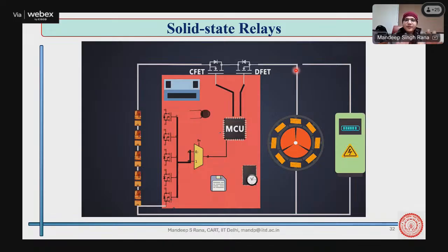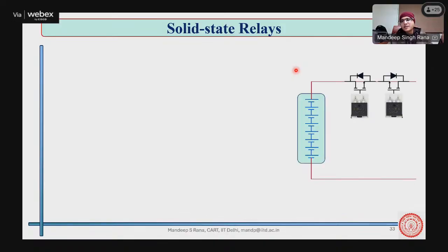So once we recognize that it is a charging or discharging condition, we turn on both FETs, because we do not want any overheating due to the diode. But first we need to recognize which to turn on first. After some time, the second one is turned on just to help the situation out. So it is something like this.